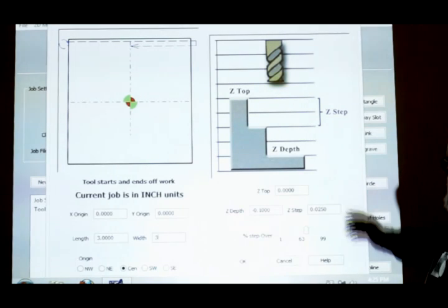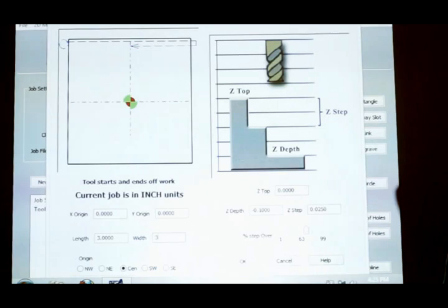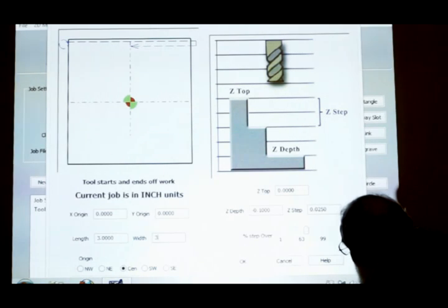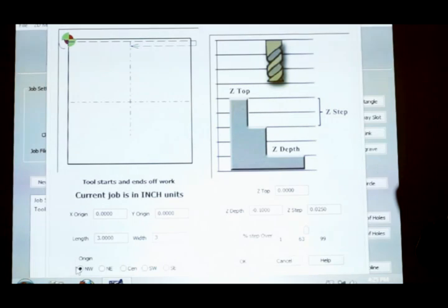And that shows up through everything. Most of the jobs have this origin. You get to specify where the origin is relative to this thing I'm doing. In this case, center is checked, but I could say that I want it up in the northwest corner. I put it in my vise, and I've indicated off this upper left-hand corner. So if my origin is up there, then I'll calculate all of the G-code based on that origin.